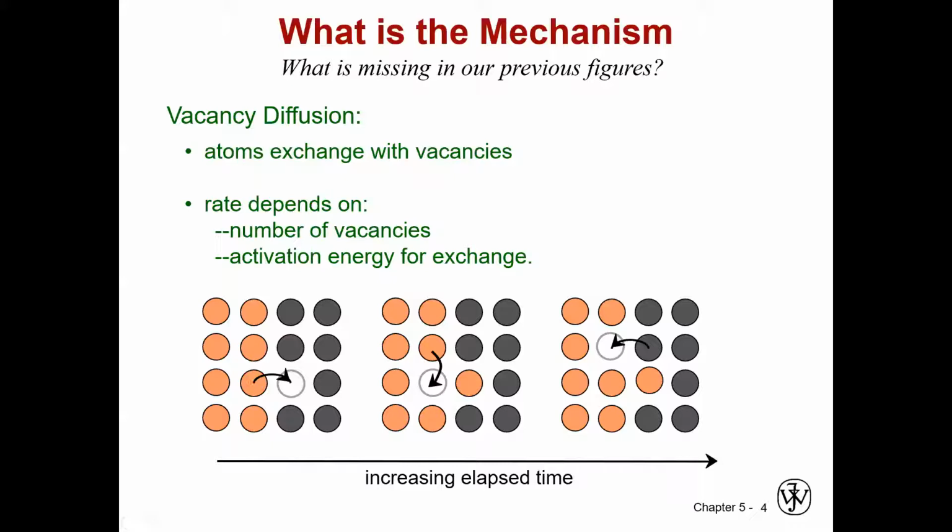And so this means that there is an energy barrier for this process of diffusion. Okay? So we're going to get another Arrhenius equation like we saw for the number of vacancies. In this case, the Arrhenius equation is going to describe the rate at which we get diffusion, how fast this process occurs.